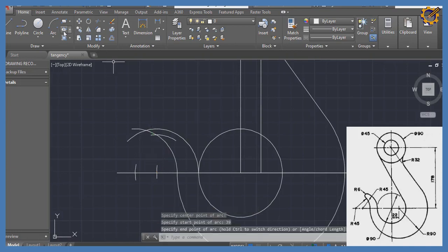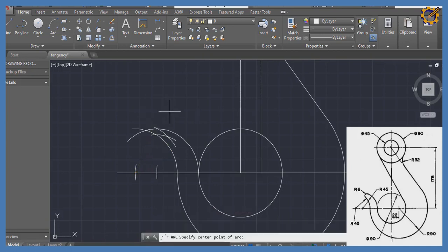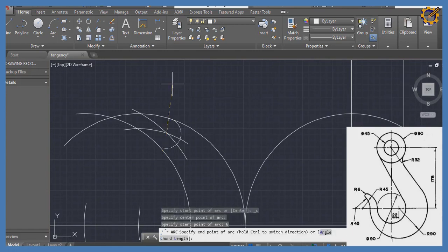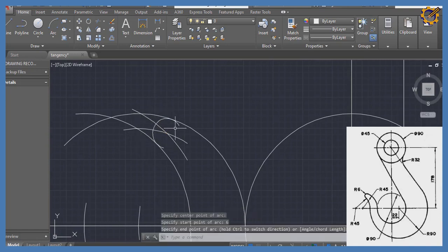arc right there. So picking my arc, 45 plus 6, that's 51. Standing right here, coming right here with 51, I enter, so I draw my corresponding arc. Then picking my arc, standing right at this midpoint right here, coming right here, radius 6, enter. Then I'm having this, pressing my control, I'm having this. So having that, now I'm going to trim off those areas I don't need.